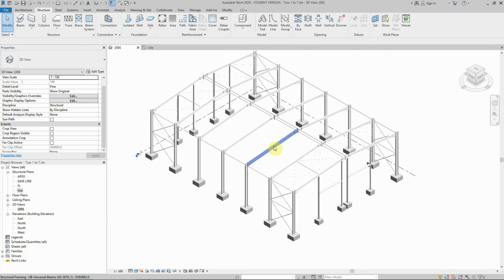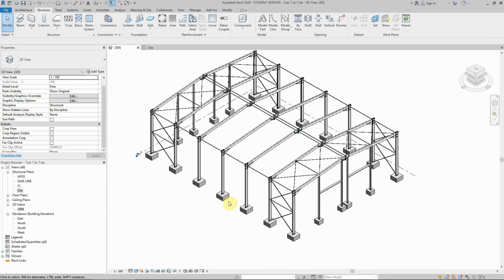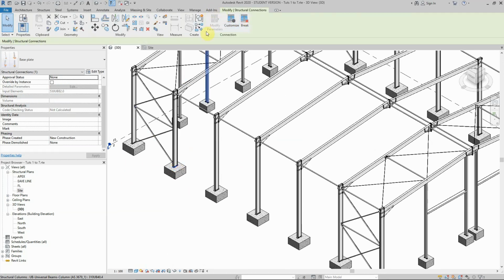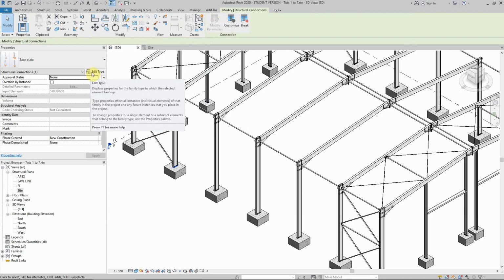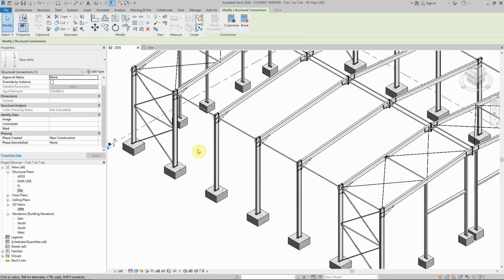Okay, so this will conclude the base plate design. We learned something very important, guys, because we agreed that this function is not activated and we are doing the edit from here. As you've seen, if I edit a connection, it will be a permanent edit on this particular project, by the way. On other projects it won't be, so now we can't reuse this connection in the old configuration if you don't duplicate it before you start editing it. So the first step for anything, please duplicate it and then start editing the connection.